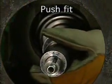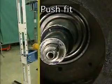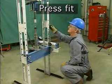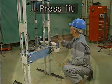A push fit is a fairly loose fit. Usually a ring that has a push fit can be pushed into place by hand. A press fit is much tighter. More effort is needed to press the ring into place. A press fit is also called an interference fit or a shrink fit.